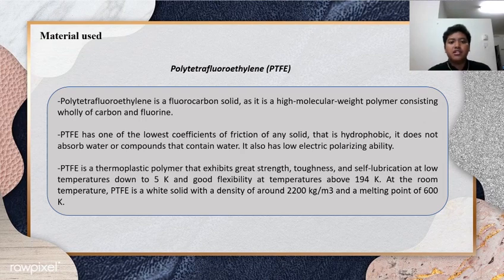The material we use is polytetrafluoroethylene. Polytetrafluoroethylene is a fluorocarbon solid, a high molecular weight polymer consisting fully of carbon and fluorine. It has one of the lowest coefficients of friction of any solid. It is hydrophobic, so it does not absorb water or compounds that contain water. It also has low electric polarizing ability.